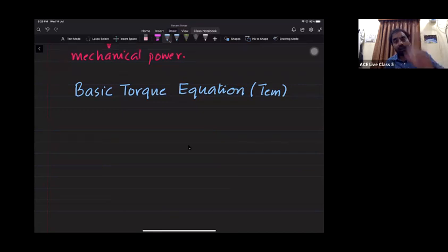If a current carrying conductor is placed under a magnetic field, that conductor will experience a force. Your DC motor works on that principle, induction motor works on that principle, even your synchronous motor works on that principle. Now I need to find out the magnitude of the electromagnetic torque of a particular induction motor when it is operating at some slip, when the rotor circuit parameters are given. So we are trying to derive an equation to calculate the values numerically using the equivalent circuit parameters.